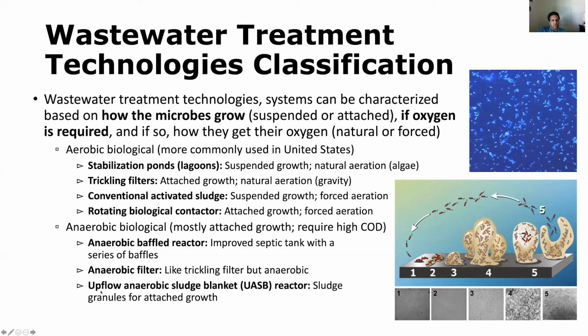Another technology used, especially in tropical climate countries like Brazil and parts of India, this technology has become very popular: the upflow anaerobic sludge blanket reactor. This utilizes an anaerobic treatment process with attached growth on sludge granules.